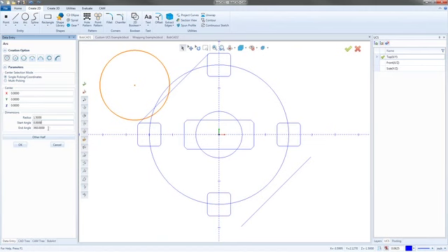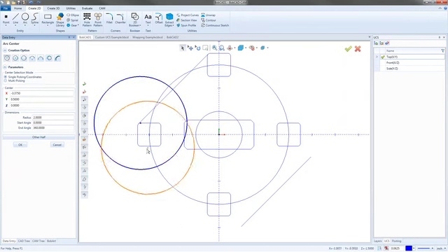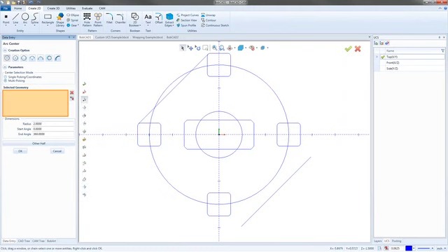And then we have our start and end angle. Now, the big thing with this is if you look at this function, the way I would usually say this is comparable to the previous versions. This is like a snap function combined with the coordinates function. Because you can go in and just snap it onto a point. So it'll always snap onto points. It'll also let you do multi-picking. So multi-picking is really nice if you have a bunch of points on the screen and you need an arc for every single one. The multi-point sketch, you just pick all the points and it throws an arc on every single one of them, which is pretty cool.